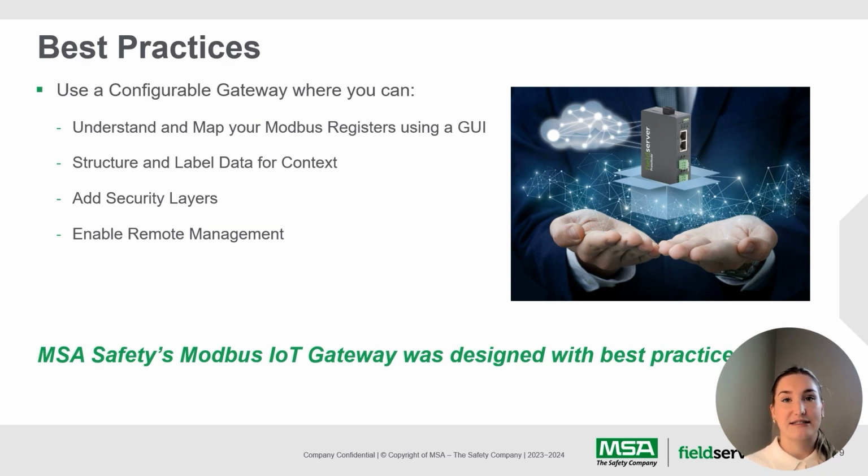Next one would be to add security. TLS certificates and access control, like we've mentioned before, are a critical piece and often overlooked. Modbus as a protocol is not secure, as we mentioned before, and you want to look for gateways that have this security built in, just to protect yourself from outside threats.